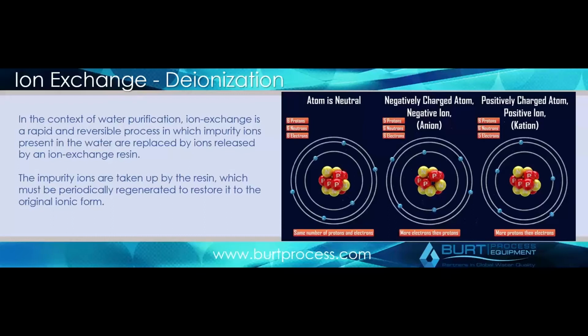So ion exchange can pull out a lot of the same things that an RO can, but really it's designed to focus on the very specific ionic content which will pass through your RO. And this will move you out of the resistivity range you typically see off of an RO, which is maybe a half a megaohm or less, up to 5, 10, and even up to 18.3 megaohm in those cases.